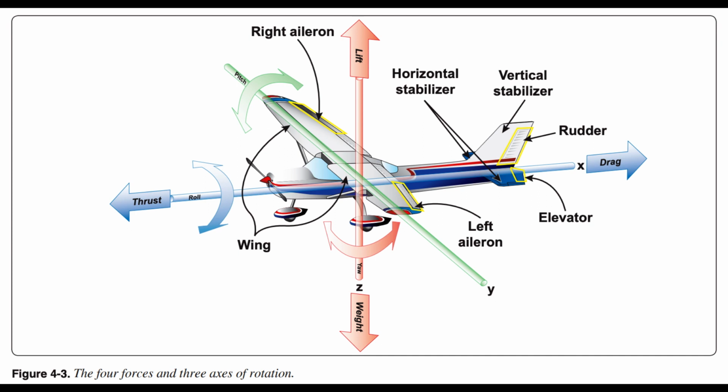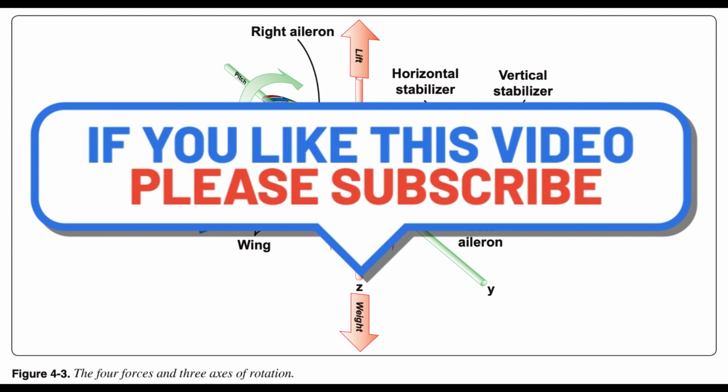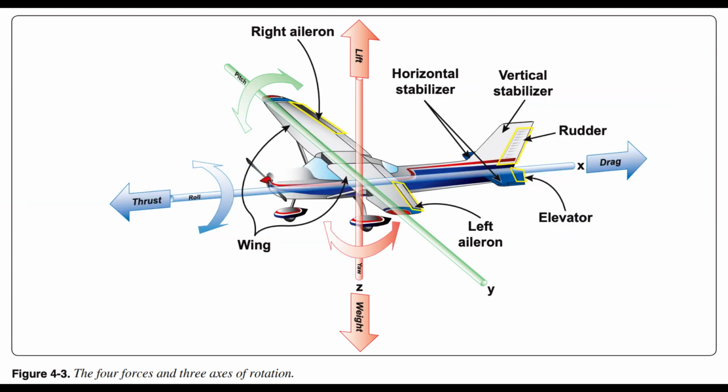Covering the entire wetted surface of the aircraft is a thin layer of air called a boundary layer. The air molecules on the surface have zero velocity in relation to the surface. However, the layer just above moves over the stagnant molecules below because it is pulled along by a third layer close to the free stream of air. The velocities of the layers increase as the distance from the surface increases until free stream velocity is reached, but all are affected by the free stream.